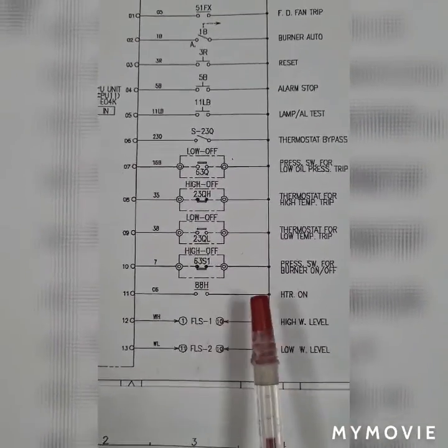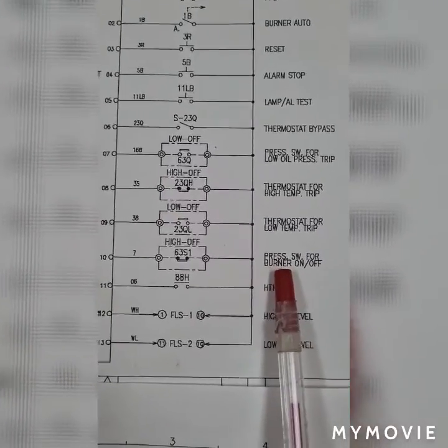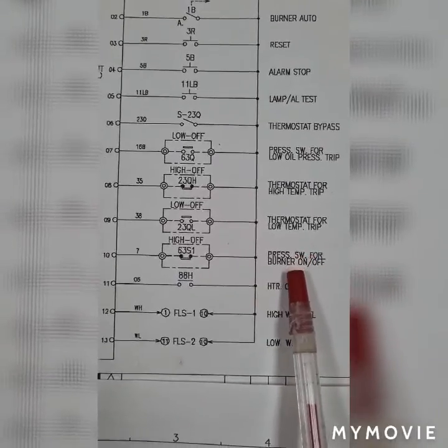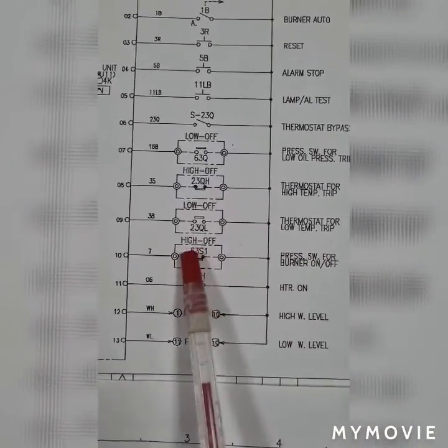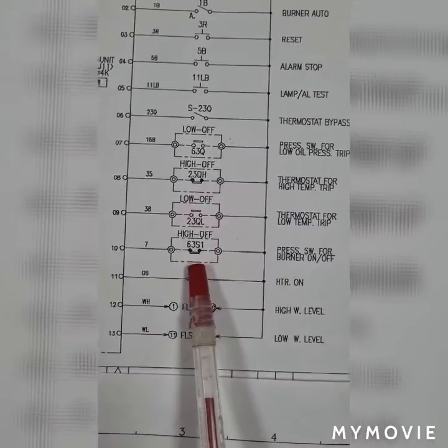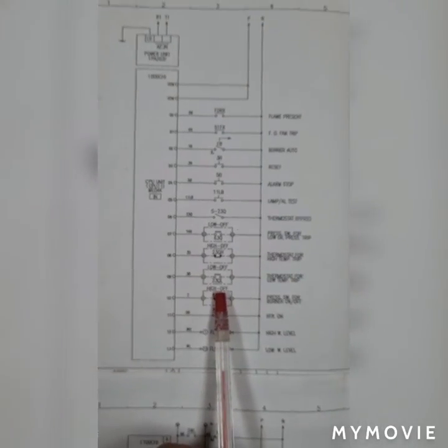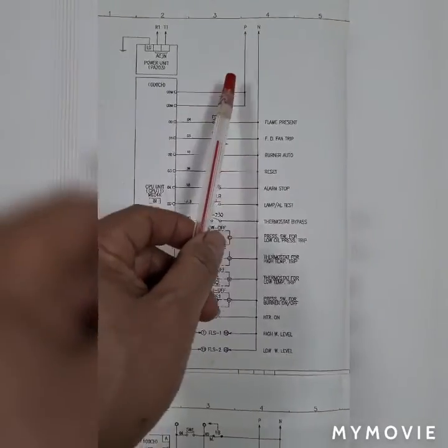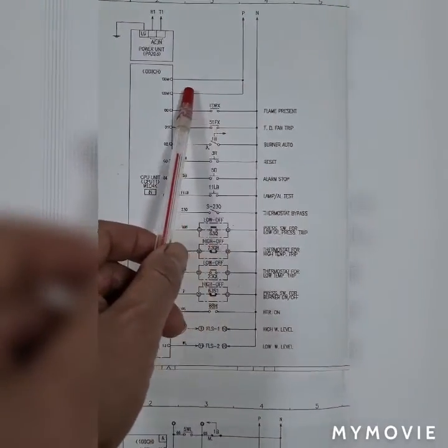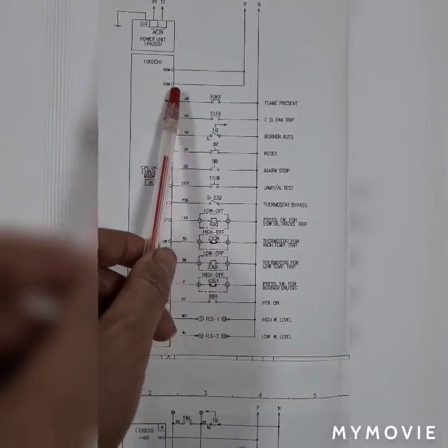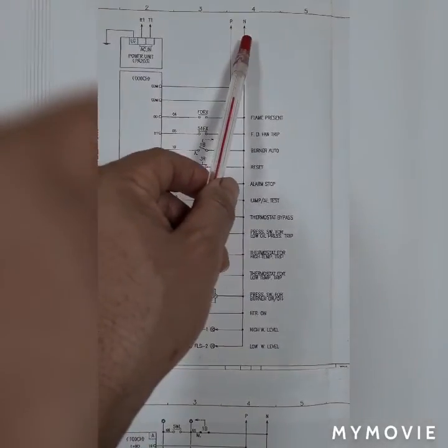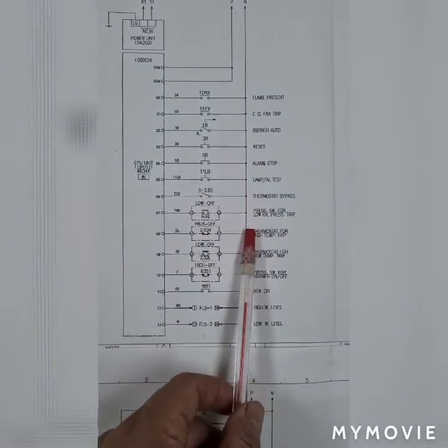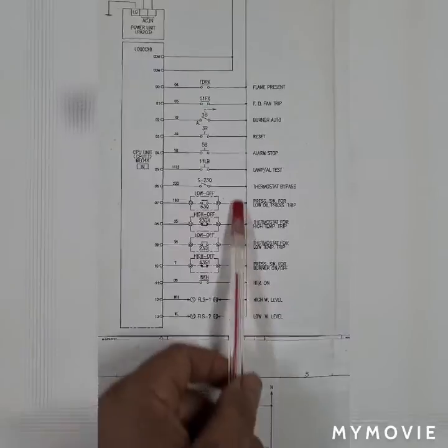When the pressure drops by 0.47 megapascal, the pressure switch monitor will close. When this is closed, the unit has positive supply going to the common and negative contacts on these devices.